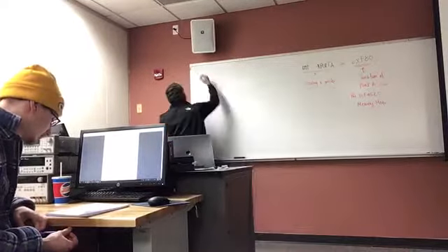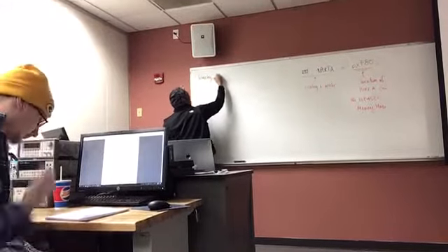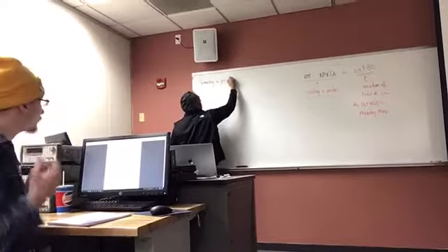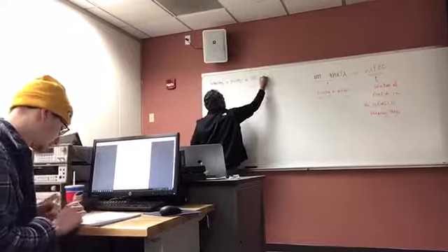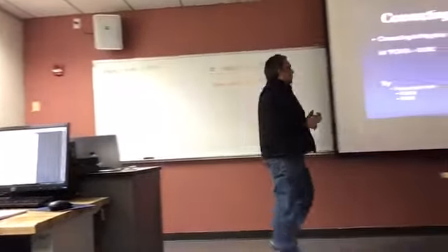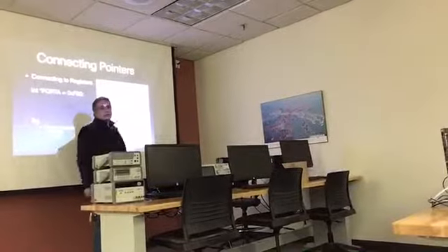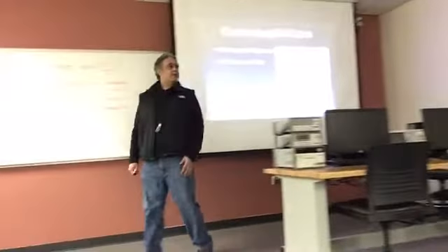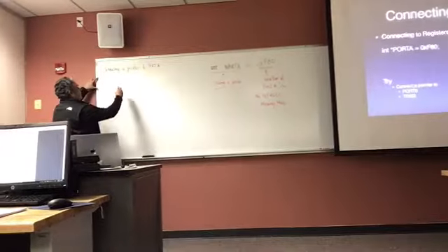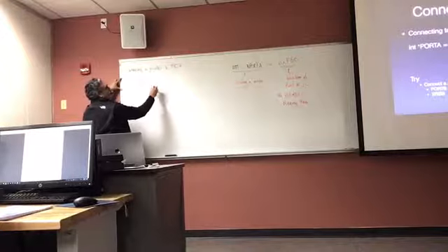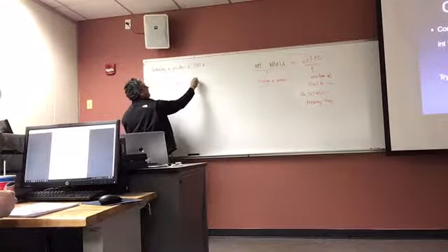We'll do connecting a pointer to port B. Okay, so if I go to the memory map, port B is located in hexadecimal F81. All right? So, how do you write it? Anybody can guide me? Int asterisk port B equals 0x F81.